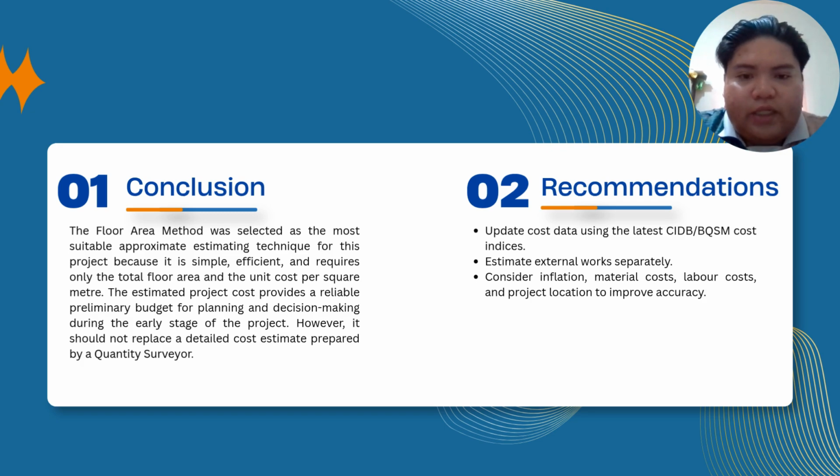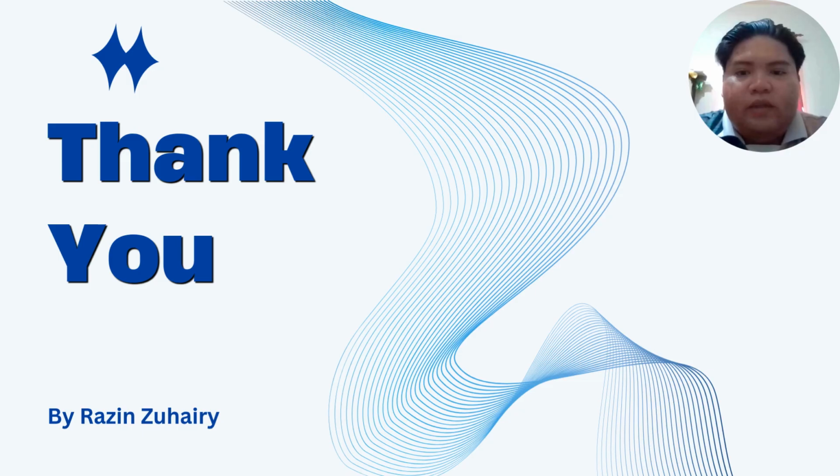Lastly, recommendation. Update cost data using the latest CIDB or BQSM cost indices. Estimate external work separately. Consider inflation, material costs, labor costs, and project location to improve accuracy.